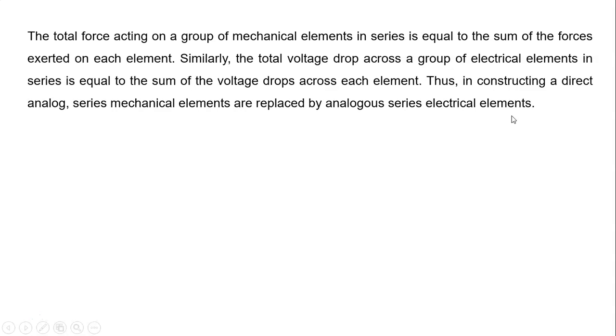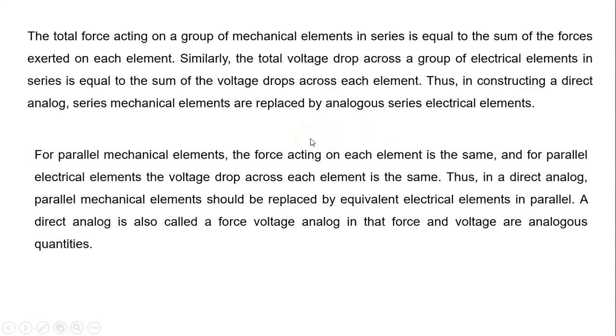Therefore, while constructing a direct analog circuit, what we have to do? We have to replace series mechanical elements by series electrical elements and parallel mechanical elements by analogous parallel electrical elements. Similarly, same thing has been written here for parallel mechanical elements.